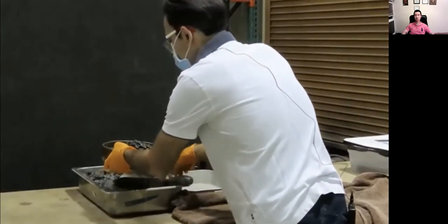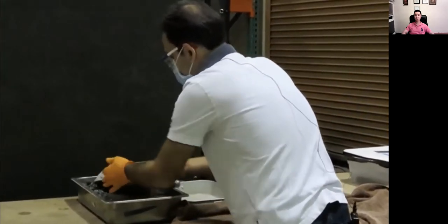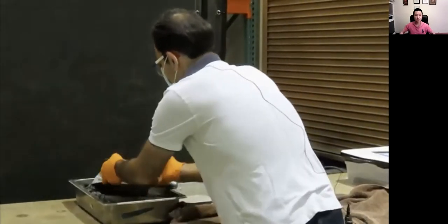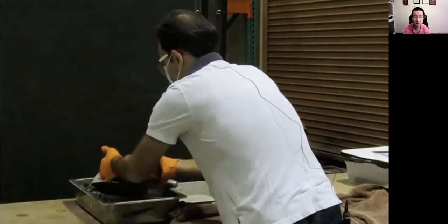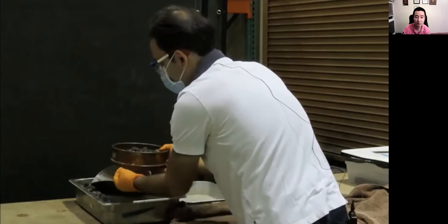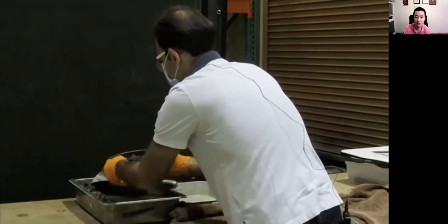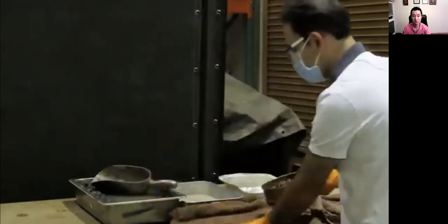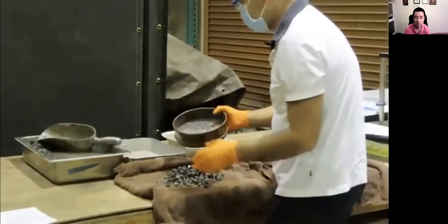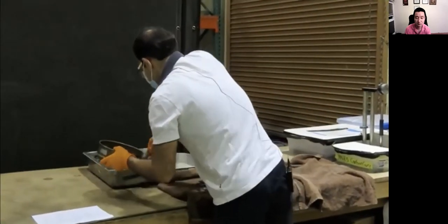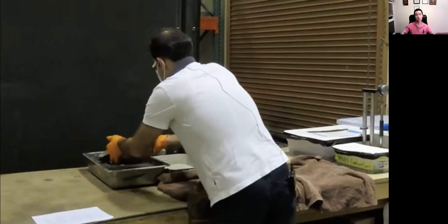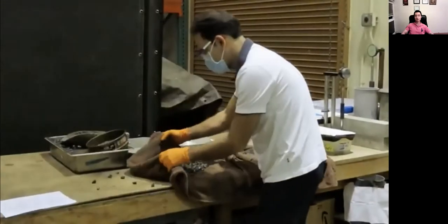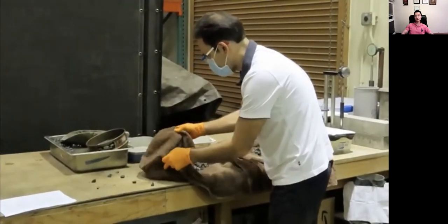dump my coarse aggregate. So I can use this sieve to drain the sample as much as possible, and then get rid of the particles smaller than the holes on sieve number 4. And dump it on the towel. And try to dry the surface as much as possible.